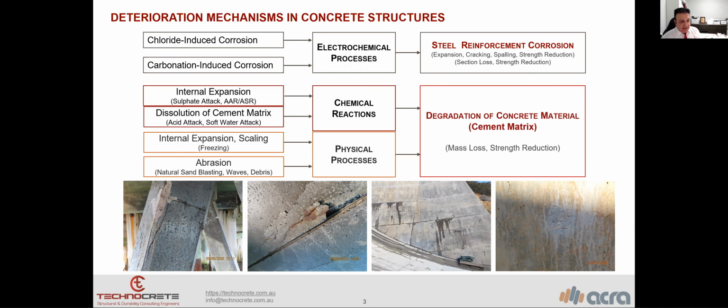Then chemical reactions and physical processes both attack the concrete matrix. Then we will have degradation of the concrete matrix, mass loss, and strength reduction. All of these deterioration mechanisms can be classified as durability problems, but at the end, they will be converted to structural performance issues and a reduction of the structural strength of the structure. That's why when we say durability problem, in the long term, it can be converted to a structural problem.